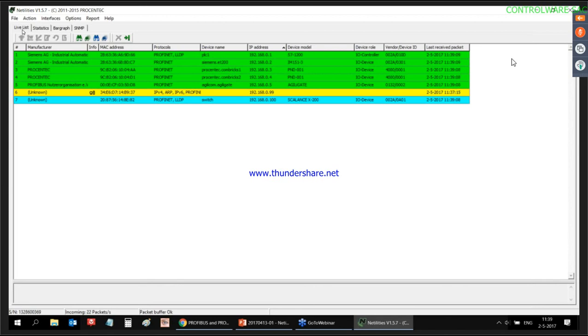Be careful. We saw that some switches do not support SNMP, even if they are managed. So when you pick a switch for your network, be careful. This is more a designing thing, but the switch is the most important part of your network after the PLC. So you need to be really careful that it's capable to handle all the communication fine.